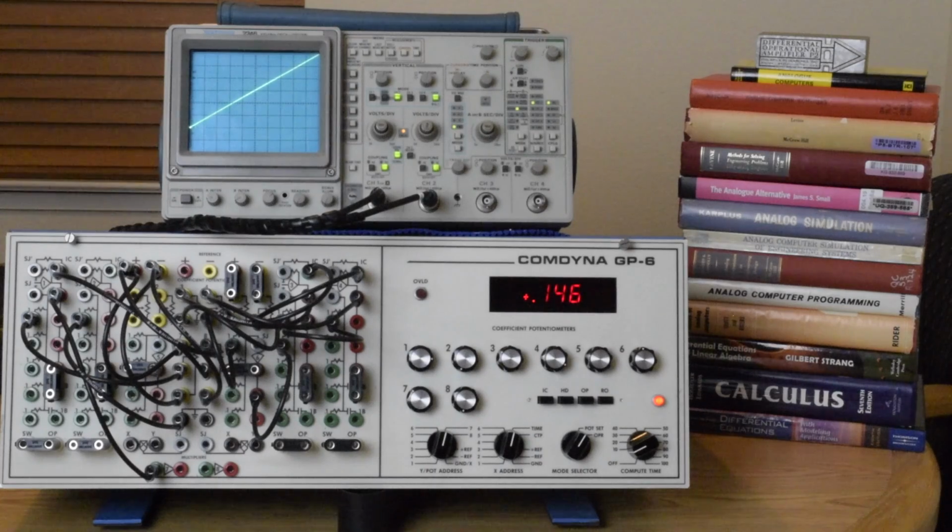In the analog computer, scaling is a little more complicated because in some cases, if you just used a factor of 10 scaling, your problem would either be too large or too small, and either one of those conditions can cause a problem. If it's too large, your amplifiers will overload and your problem will not be correct. If it's too small, you'll be operating in the noise range of the amplifier, and that will also have a chance to introduce an error. So generally you want to keep the solutions and all of the variables as close to the mid-range as possible, I guess would be a simple way to say it.